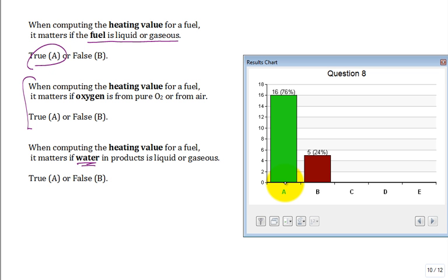Where does that water go? Well, they can collect it, and guess what? In the middle of winter, if your outside air is really cold, it's also very dry. You ever had static problems in your houses in the middle of winter? You just walk around, you touch the doorknob, zap. In the summer, do you have that problem? You ever get a static electric shock touching the doorknob at your house after you walk across carpet in the middle of summer? No, it's not dry at all. It's humid. You just sit there and sweat. But in the winter, it's dry. So guess what? Heat in the house, great. A little extra water vapor in the house, no sweat.